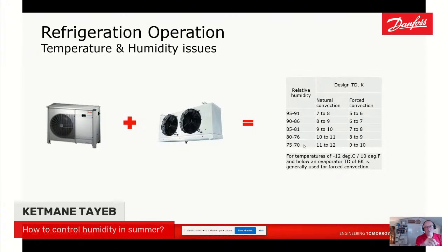If your humidity is too dry, there are third-party systems that actually give humidity into the room. Danfoss, as far as I know, we don't make that product, but there are ways to do it. There's also things like desiccant wheels, but that's more AC, big rooftop type systems to remove the humidity out of the air.